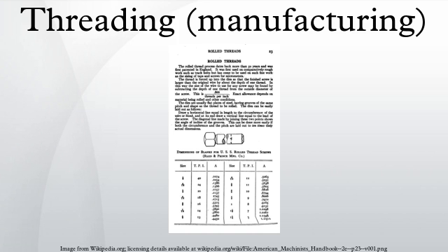This was formerly arranged mechanically, and it was suitable for mass production work although uncommon in job shop work. With the widespread dissemination of affordable, fast, precise CNC, it became much more common, and today internal and external threads are often milled even on work where they would formerly have been cut with taps, die heads, or single pointing. Some advantages of thread milling, as compared to single-point cutting or taps and dies, are faster cycle times, less tool breakage, and that a left or right-hand thread can be created with the same tool.